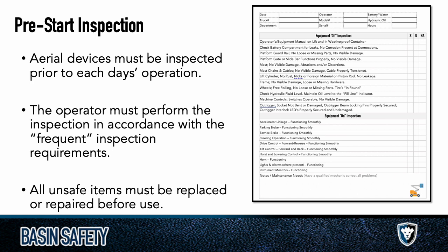And the other thing about both forklifts, I didn't mention this before, but aerial lifts as well, super important. A lot of people skip this, I've noticed on the inspection, is air pressure in the tires. Especially if they're an inflatable tire, some of them are solid, so it's not an issue. But if you have an inflatable tire and one of them's flat, I promise you, it's going to affect how safe you feel in that equipment. It's going to affect how much you can load it, how quickly and easily it moves, how bouncy the ride is. Make sure your tires are full.